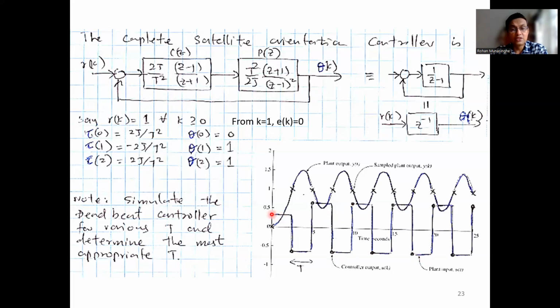You can see, when you do that, look at the initial case. When you exert a torque and keep it there, for one sampling interval, the satellite starts to turn like that. And it comes exactly to 1 over here after one sampling interval. So you wake up and see, fantastic. The heading is exactly what you expected. Heading is 1. Okay. So then what you do is you calculate the torque, how you want to adjust the torque.